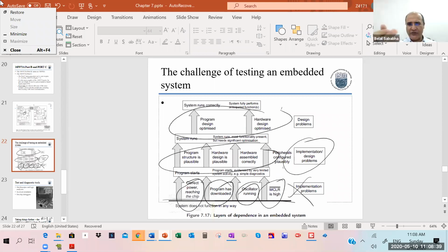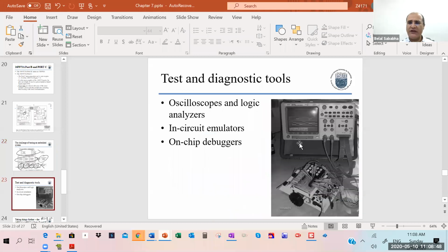You could do single stepping through the debug tools, like the ones we used with Microchip, or you can use hardware tools, like a scope. I always tell the students, when I walk into the embedded systems lab and they are all shocked that their thing is not working, I ask: where is your oscilloscope? I don't imagine anybody designing and debugging an embedded system without an oscilloscope. It is a very helpful tool to diagnose problems.